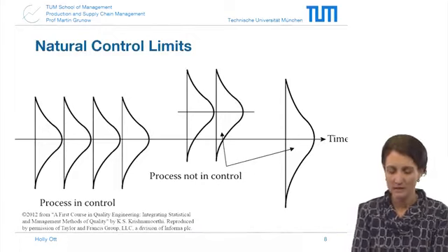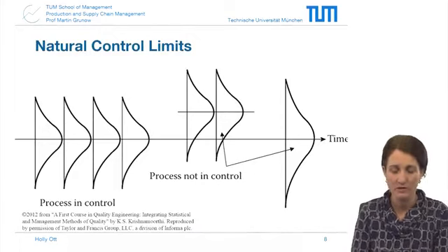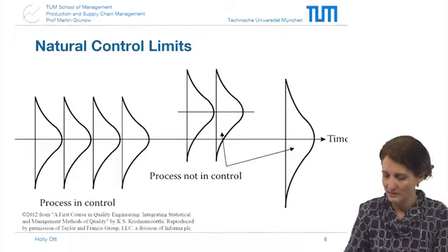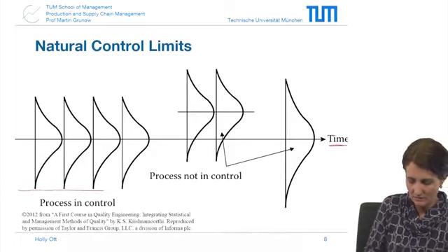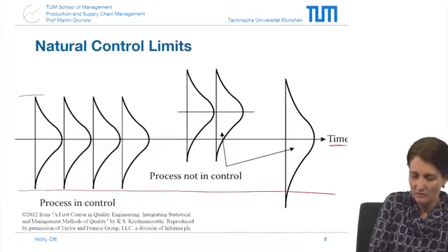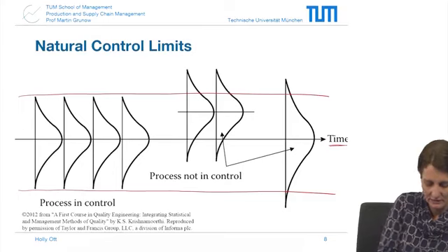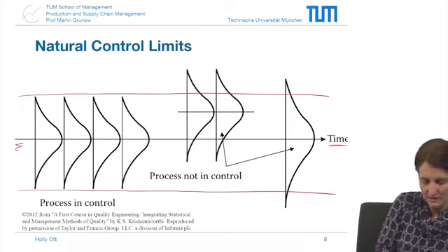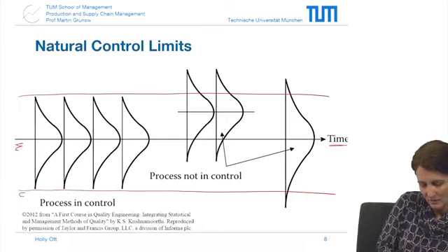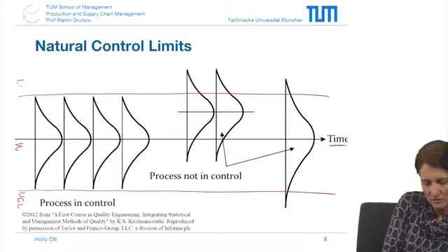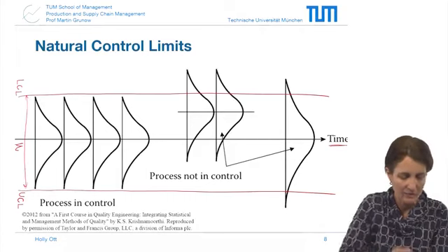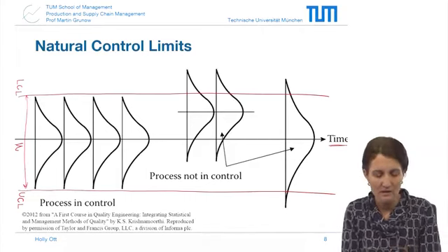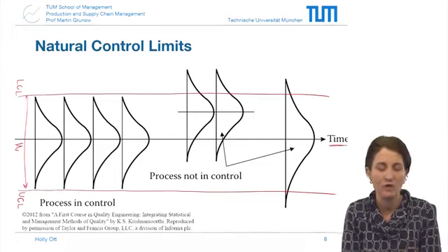So now let's look at this more practically. Let me draw this. Here we have a process, a normally distributed process with time, and we would then construct our 3 sigma limit. So if this is the mean, it's hard to write sideways, this would be your upper control limit and your lower control limit there. And what we expect is that 99.73% of our values will fall between those 2 limits.